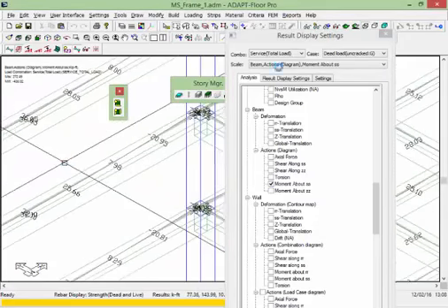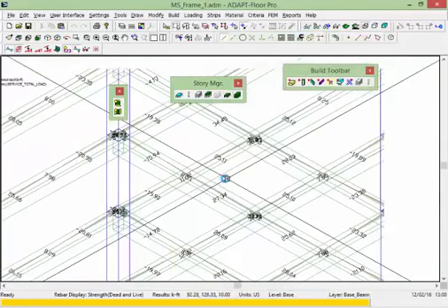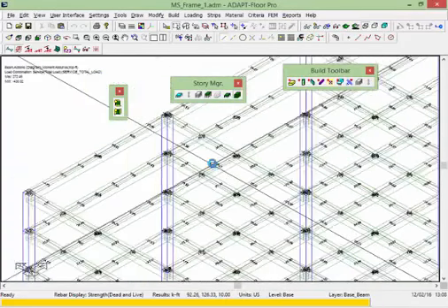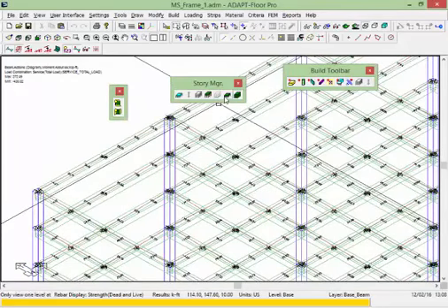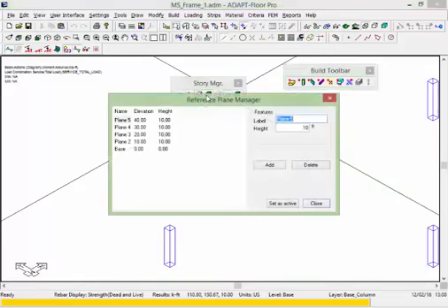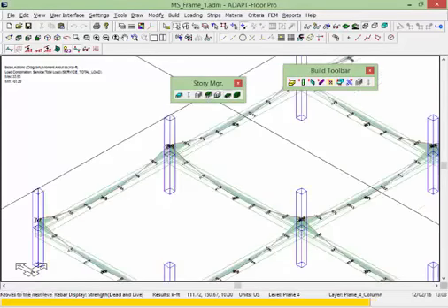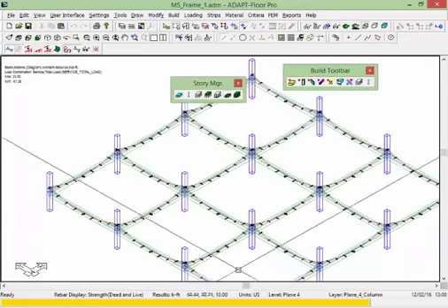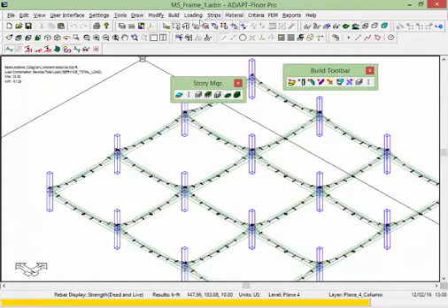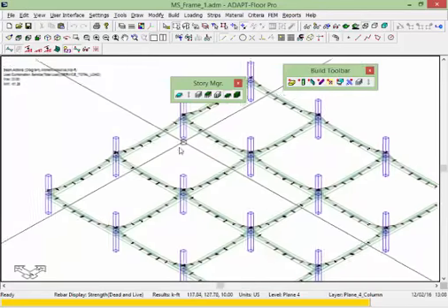So when you have a skeletal structure to interpret and see some of those results, there are ways that we can filter. The first, kind of the highest level of filtering, is to go to single level and to navigate to the level that you would like to review. And then we can also use some options from the selection toolbar to filter viewing. So different ways to view moments in that.